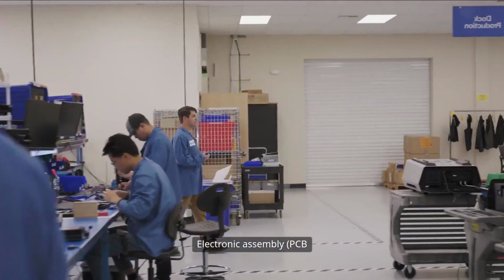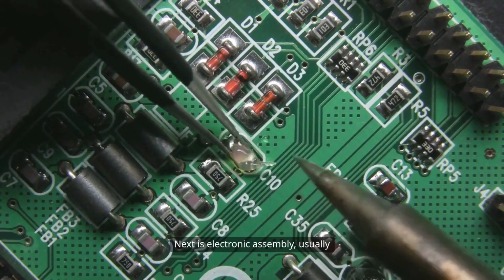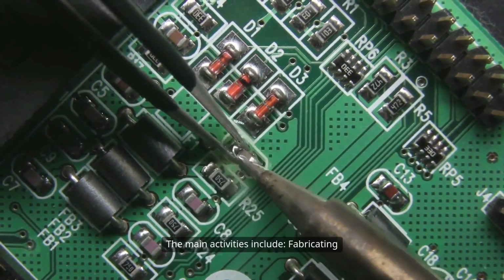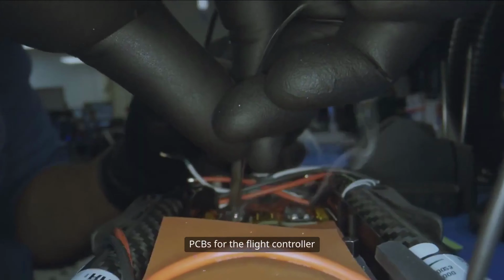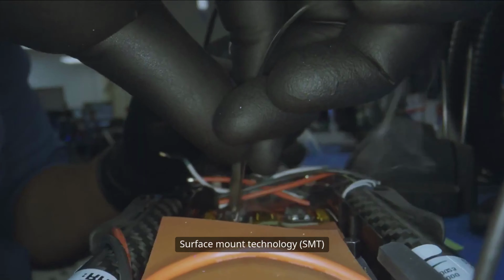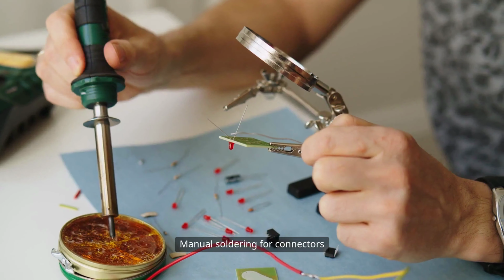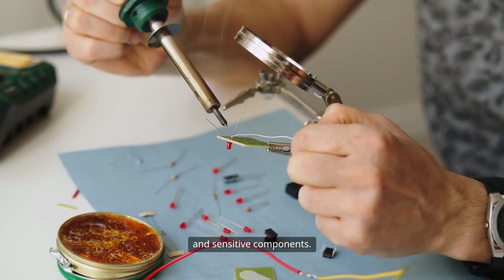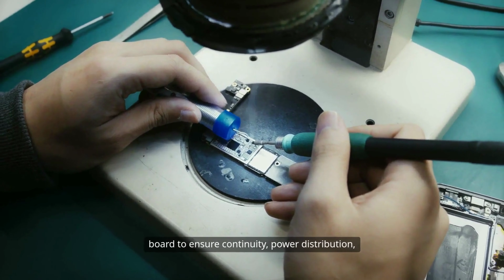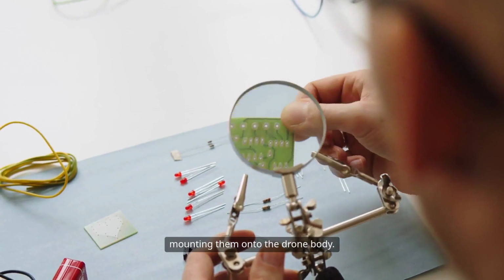4. Electronic assembly, PCB fabrication and soldering. Next is electronic assembly, usually carried out in a clean room environment. The main activities include fabricating PCBs for the flight controller and power distribution board, surface mount technology, SMT, soldering of electronic components, and manual soldering for connectors and sensitive components. Technicians inspect each circuit board to ensure continuity, power distribution, and signal integrity before mounting them onto the drone body.